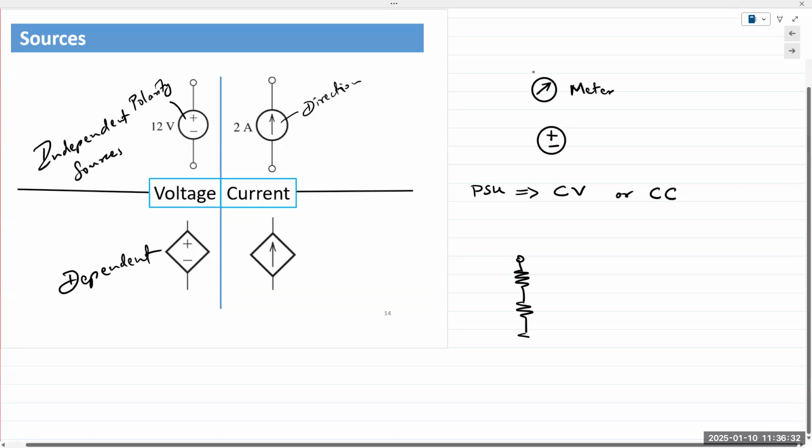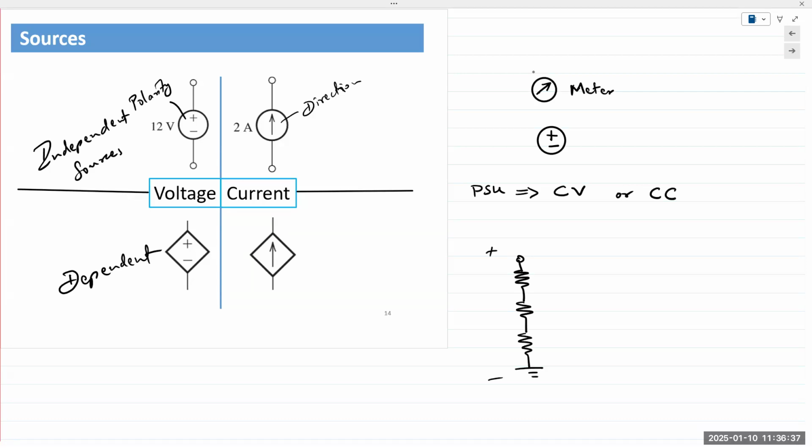If you apply a voltage to a series connection of resistors, let's say you supply 10 volts between the outer terminals, right? Let's actually make it 3 volts. 3 volts applied from the top to the bottom series connection of resistors, and all 3 resistors are equal. Let's see, R ohms, R ohms, R ohms. What is the value of the voltage across each one of the resistors? 1 volt, right? So you'd get plus minus 1, plus minus 1, plus minus 1.